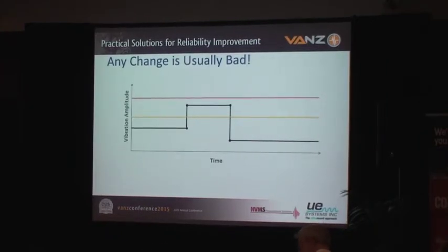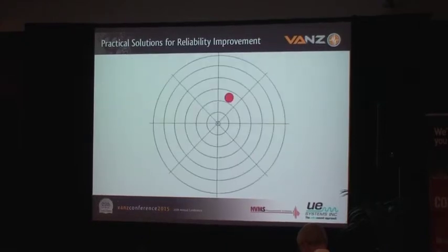This was on one of the low-pressure turbines on our main turbine generator, a 1,200 megawatt steam turbine generator. And all they had in the control room was the amplitude. Craig also had access to the phase data. Basically, I think we all know intuitively when I start telling you a little bit more about the machine, two bad things happened. If we look at it from the polar plot with the vectors, that's where the imbalance was initially. And it had been running that way for quite a while.